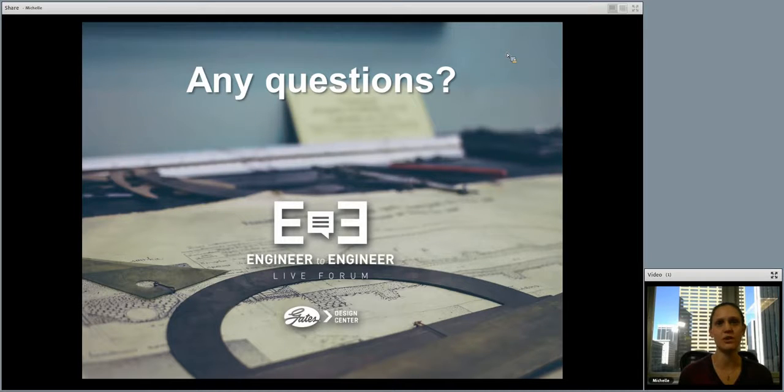Additional information is going to help you narrow down the drive options. The more information you put in, the more the program will narrow things down for you. One example is if you know your belt guard limits you to a particular diameter and width, you can add that information into the driver and driven pulley section. Then you'll only get drive options that meet those requirements.